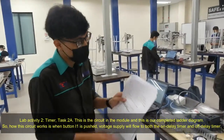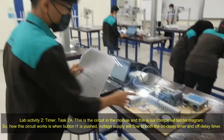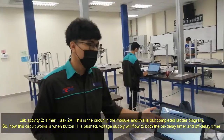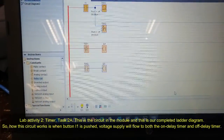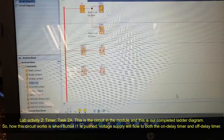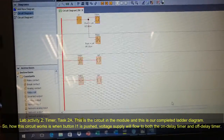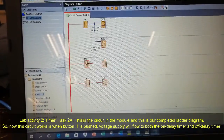Lab activity 2, timer. Task 2A. This is the circuit in the module, and this is our complete ladder diagram. So how this circuit works is when button I1 is pushed, voltage supply will flow to both the on-delay timer and off-delay timer.